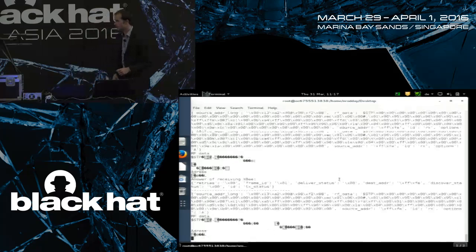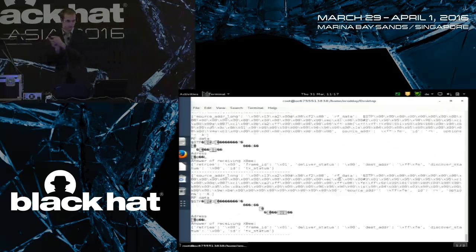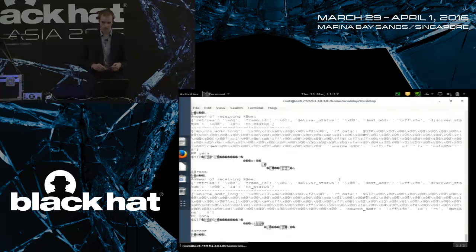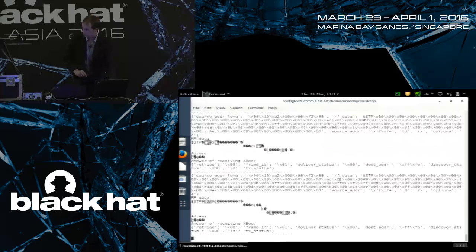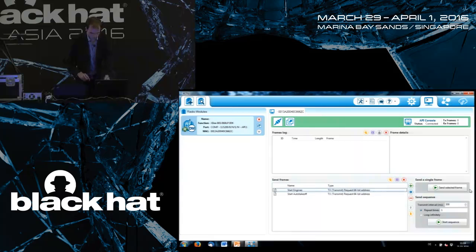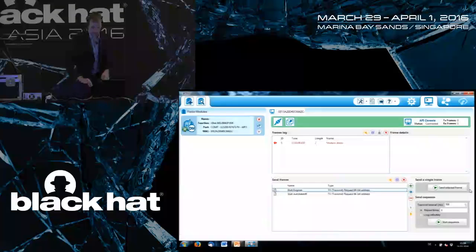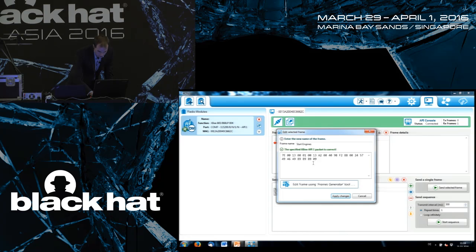I will now show the command injection attack, so that we are actually able to inject commands to the communication channel and make the UAV do something. Therefore, I need the other computer again. So what you can see here now is actually the original software from the manufacturer of the chip that is used, this XBee chip. It's called XCTU. And I saved a couple of packets here.